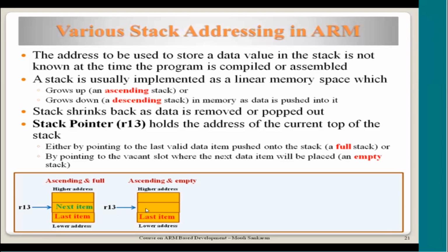So this is very specific to a processor. Now which is better? You can follow any convention because you can see that the number of operations done to push an item into the stack is the same, because either you increment the pointer after pushing this item, or you increment it before pushing the item. So based on whether it is pointing at an empty location or the full location, the incrementing of R13 needs to be done anyway for every push operation.